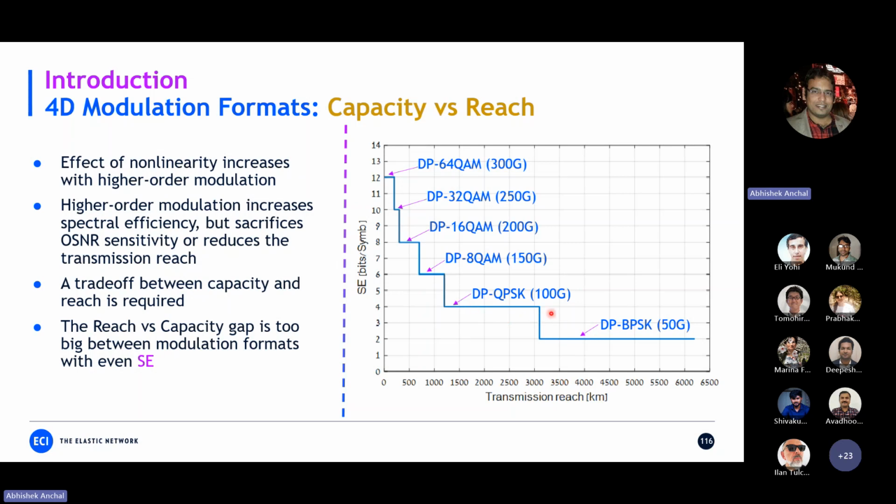So if somehow we can provide an alternative between these two higher order modulation formats, so that our spectral efficiency is not an even number, but an odd or fractional number, we can fulfill those scenarios where the OSNR is better than implementing BPSK but lower than implementing QPSK. So we can still move to better performance of the system, or let's say optimum performance in a given network, if we have an option available between BPSK and QPSK.